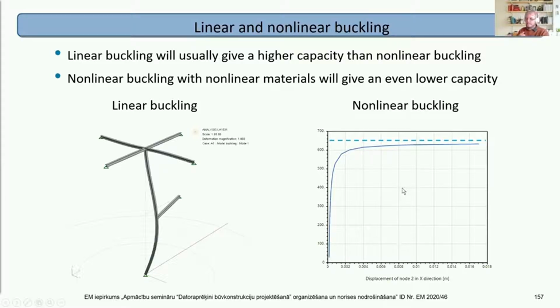Now, if you're doing design, then as a general rule, if the buckling load factor is 10 times the applied load, the buckling is not giving you a problem. If the buckling load factor is 1, then it is failed. And in between the two, it's not a factor of safety, but the buckling is affecting the capacity and needs to be taken into account.